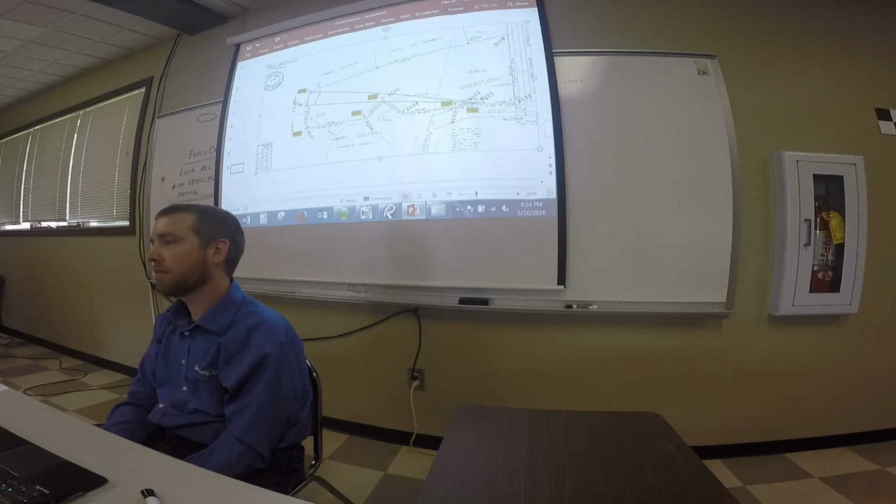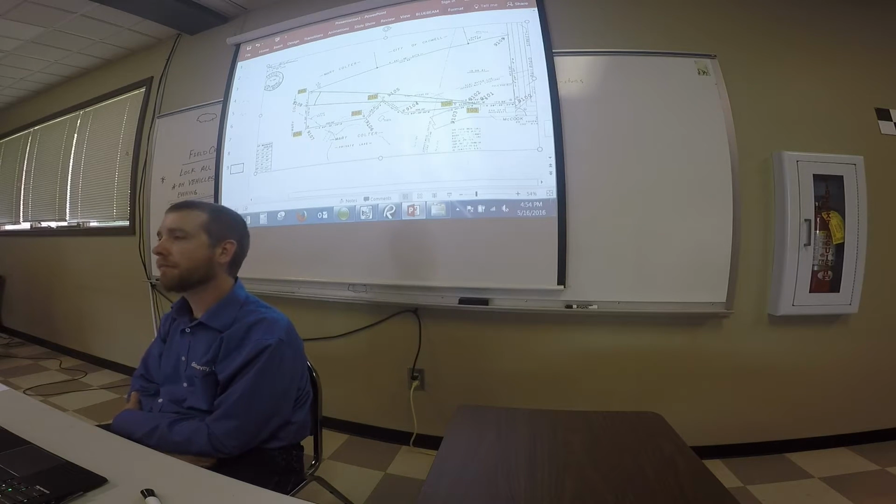So the very first thing we do is sit there at the end of the day in the hotel room, and you're going to do some inversing on the plat and on your field data. I do a bunch of different inverses and find that longest diagonal that's got a rough check. Decide, all right, there's what I'm going to use. Boom, grab it and move it to it.